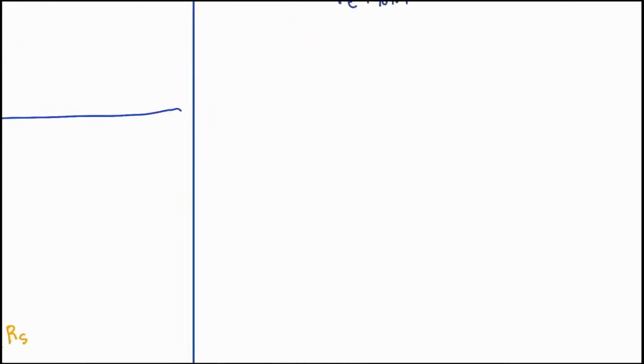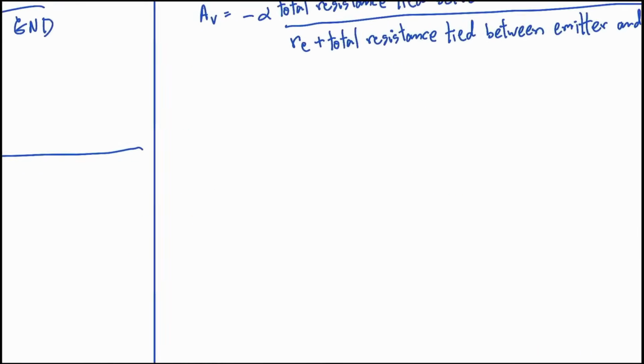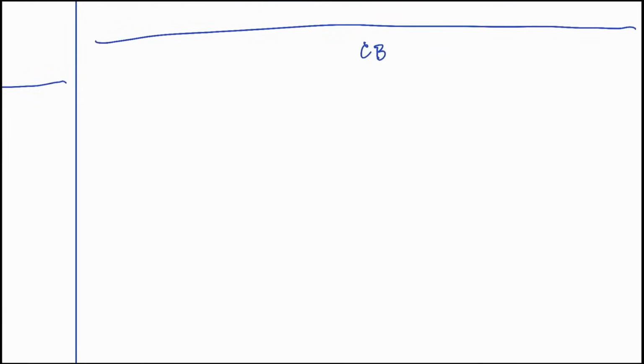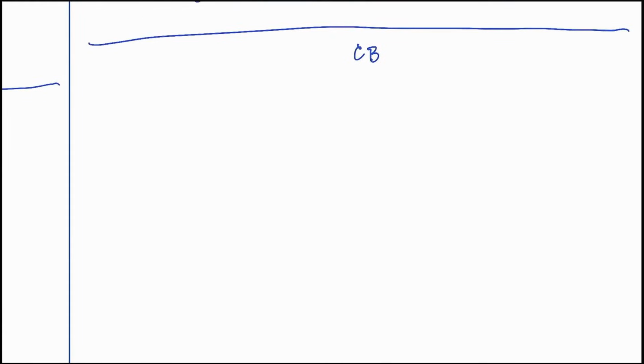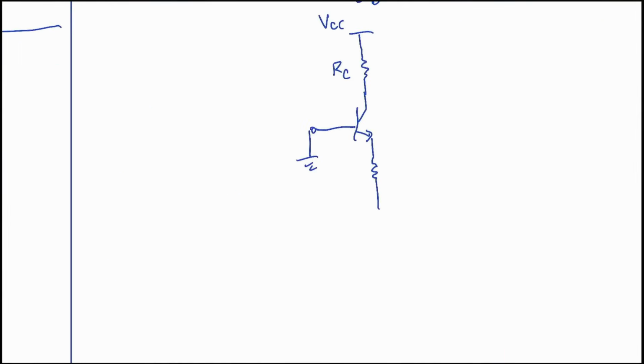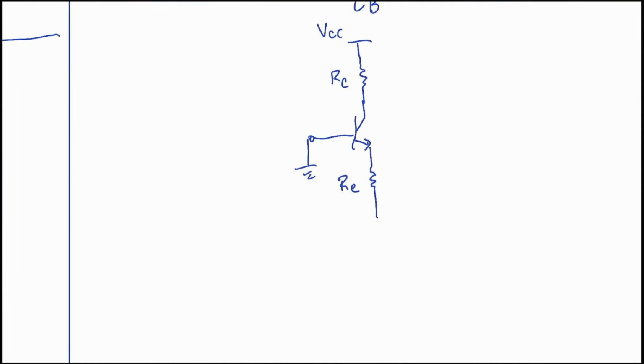Next, let's look at the BJT version. This one has a common gate, and the BJT version is not to be outdone. Next, let's take a look at the common base amplifier configuration, which is actually quite similar in its fundamental nature to the previous setup. In this specific circuit arrangement, the supply voltage VCC is directly connected to the collector resistor RC. This resistor then serves as the critical link that connects to the collector terminal of the NPN transistor, which you can clearly see positioned right here in the middle of the schematic diagram. And this part here is what we call RE. This is the output.